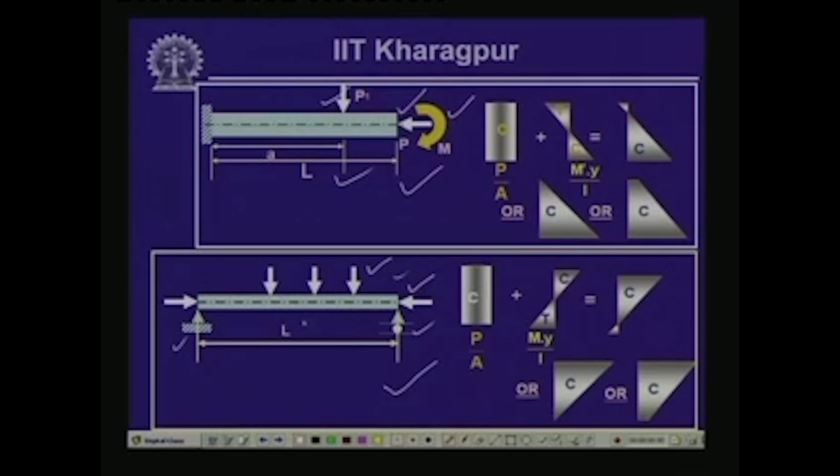If we would like to calculate stress at any cross section in the member, then the stress will be because of this axial load, and this lateral load is going to cause a bending moment M and shear force V at this particular cross section. There will be stresses because of this bending moment M and because of the shear force V, and finally we will have to calculate the resulting stress because of all three actions.